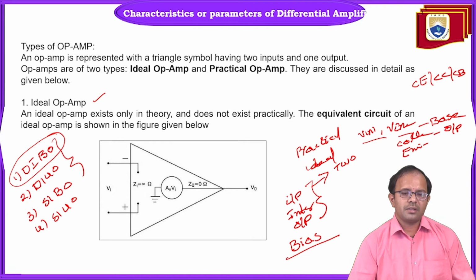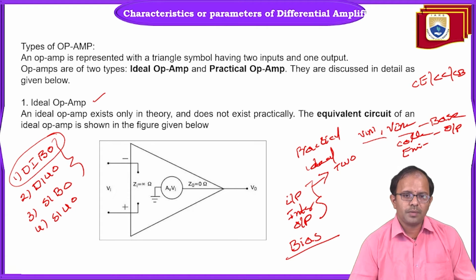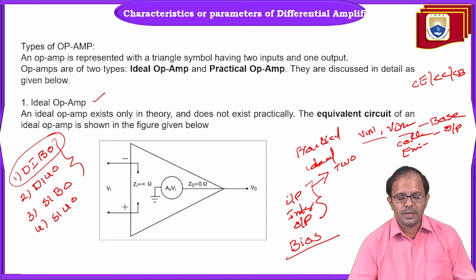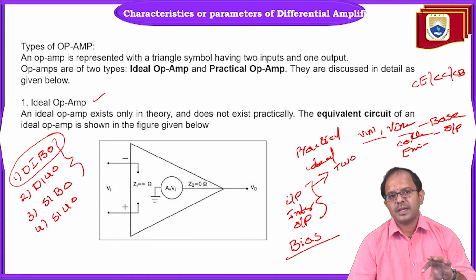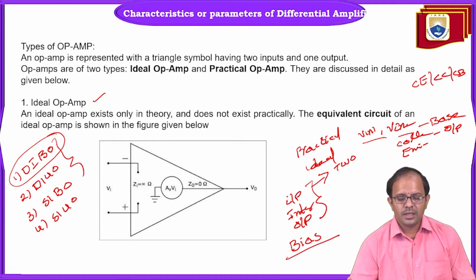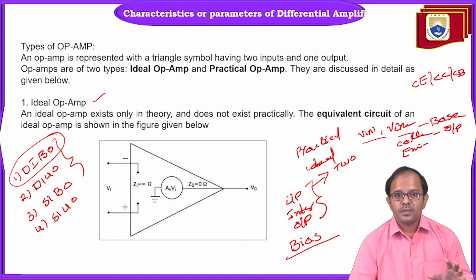So that allows you to fix the Q point. Appropriate biasing voltage is required, and this biasing will allow the Q point to be fixed in the appropriate location. That means by considering both the resistors and everything, you are going to set up the Q point as per the requirement, right?